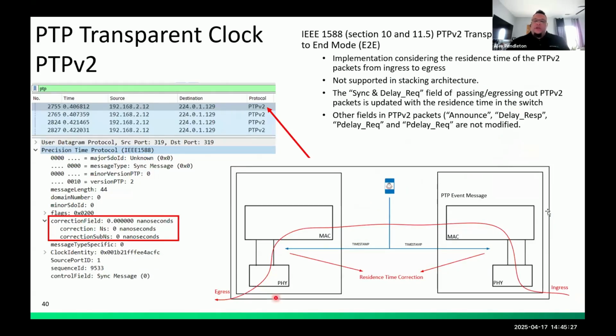To follow how this PTPv2 end-to-end process works, you take a packet of information, it goes to the PHY, which is just behind the port. So coming into a port on the switch, you go to the PHY, which is just a little coalescer of packets before it goes and gets parsed by the main controller, which is the MAC. And as that packet moves past the PHY, we begin tracking its time. And this diagram shows two MACs, but that's not true. It's still the same chip.